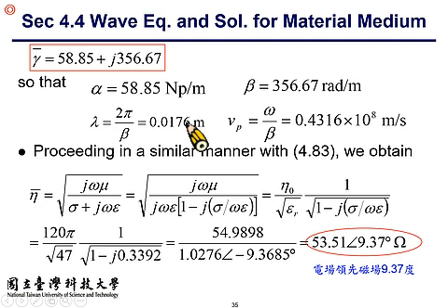Now, let me calculate this thing. The velocity. For free space, what is the phase velocity? 3 times 10 to the 8th, right? And here we only have 0.4 times 10 to the 8th. So it's about 8 times smaller. It only has 1/8 of the velocity in free space. Because the velocity is much smaller, the wavelength becomes much smaller as well. All right, so this makes sense because you have a higher permittivity.